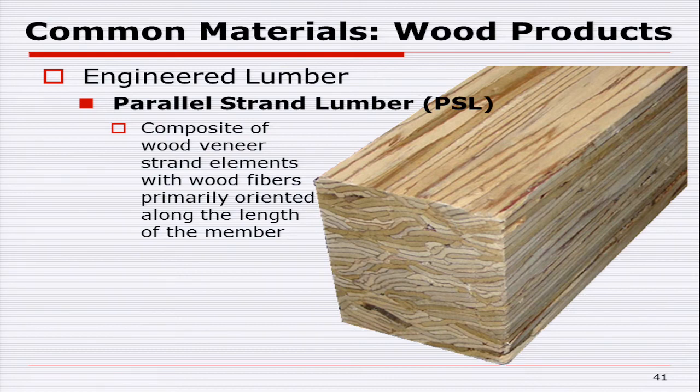This is probably the most expensive lumber that we can get, and it tends to be some of the highest strength lumber we can get. So you can look at the end grain, I'll pass one around, but you look at the end grain here and you can see it's just lots of thin strips of lumber. But these are veneers that couldn't be used for something else that got clipped up and glued together.